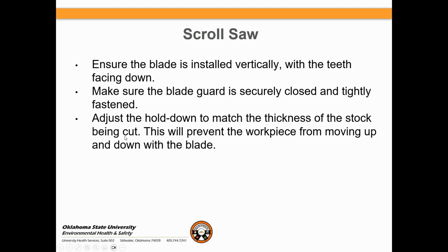Okay, if you have a blade that's dull, or a blade that has any type of a bend to it, you're going to get crooked cuts, and it almost smells like burning wood, with vapors coming off that particular cut itself.